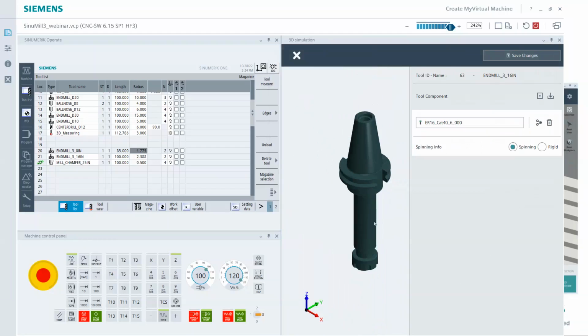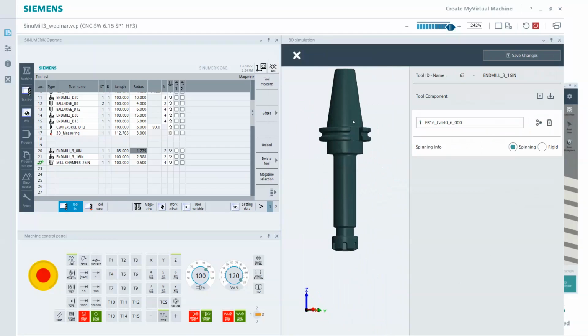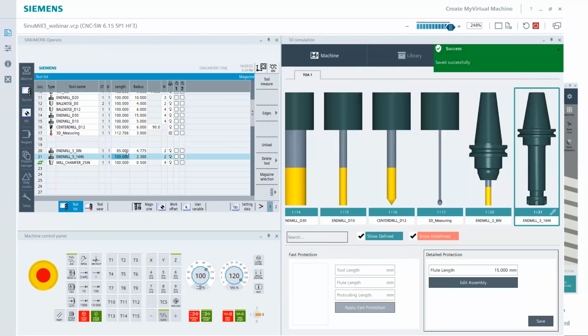Now you'll notice, where did my tool go? Tool's in there. Remember, the 100 mil is from gauge line to the tool tip. So if I need it to project out, I'm going to have to take into account this overall length plus that projection. So if I save it and I now start to increase a little more, there it goes. See now it's updating. So 200 is probably more than enough. So just keep that in mind.